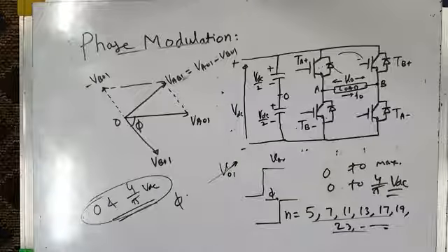And once we know the contours for variable fundamental component of voltage, and we identify graphically the contours for 0 fifth harmonic component of voltage or 0 7th harmonic component of voltage, we'll be able to find the areas, the regions, or the switching angle combinations, the locus of the point, which will give us PWM voltage waveform across the load in such a way that we will be able to control the fundamental component of inverter output voltage and simultaneously suppress or eliminate certain selective harmonics.